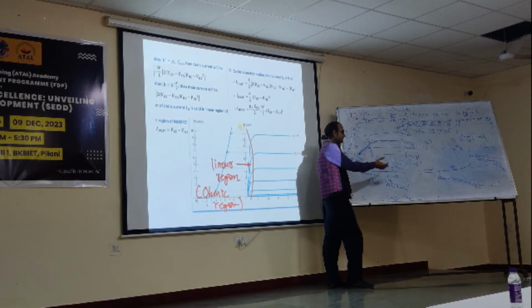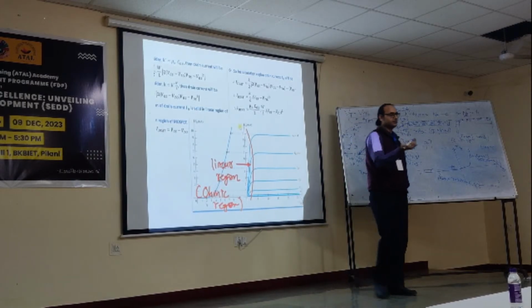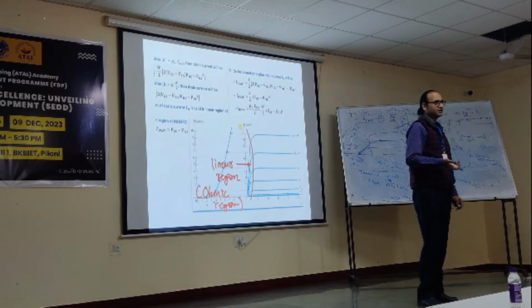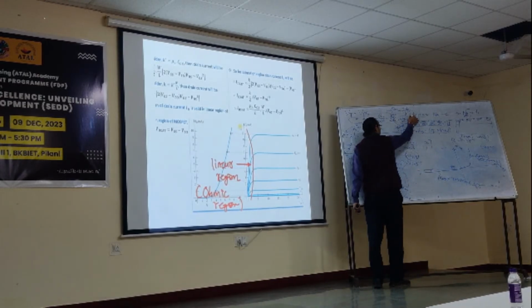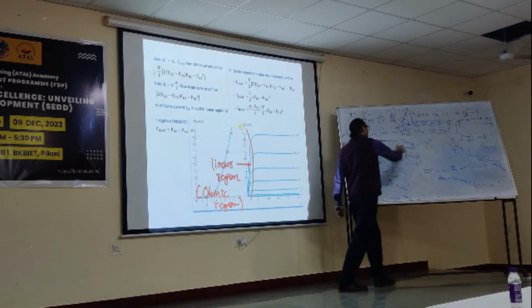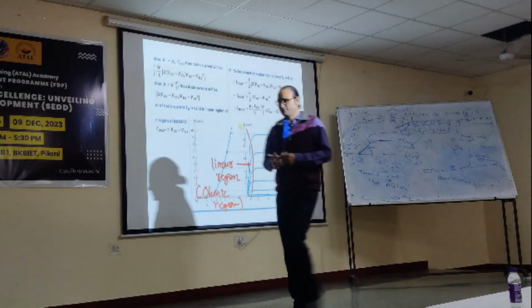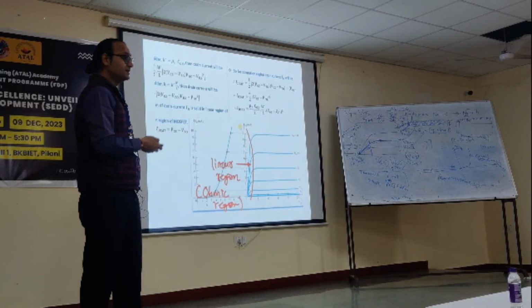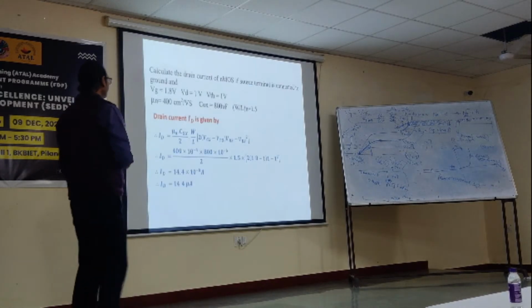If you reverse bias it too much, the junction will break down. Just like in a diode, avalanche breakdown or Zener breakdown. Obviously, avalanche breakdown will occur there. And if that takes place, then nothing is left. These currents will increase. We should not operate up to those values. They are always mentioned, specified, right?